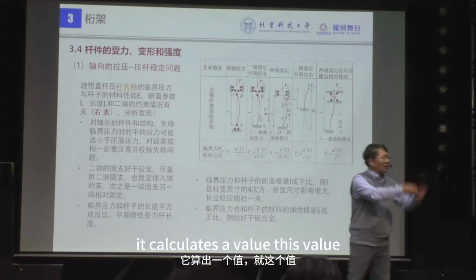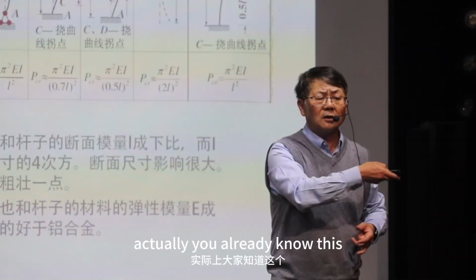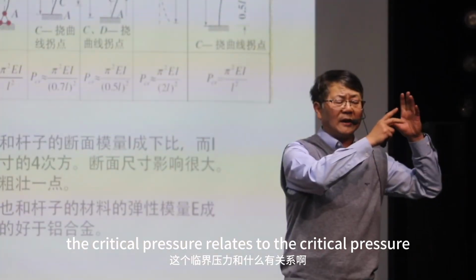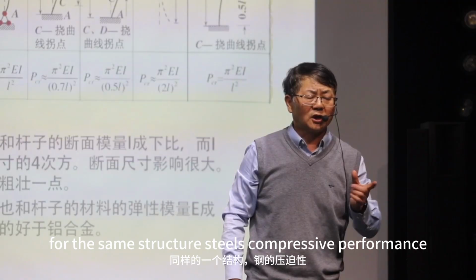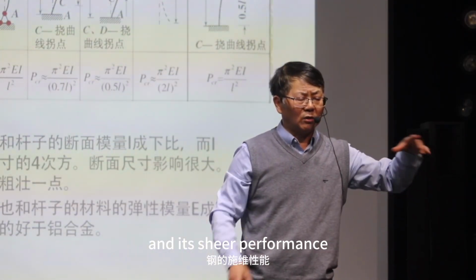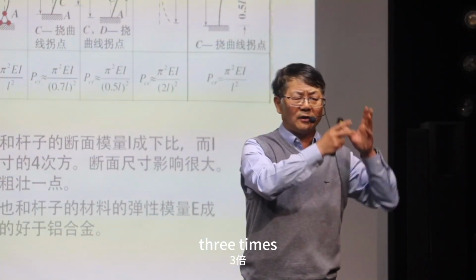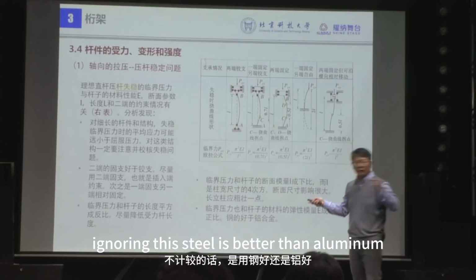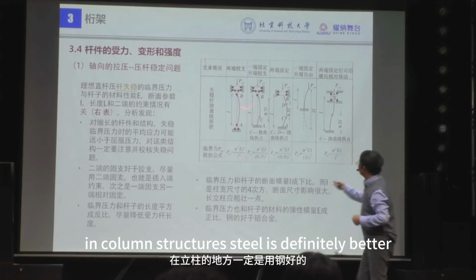It calculates a value, this value. Take a look. You don't need to memorize this. Actually, you already know this. Look here. The critical pressure is proportional to this elasticity. For the same structure, steel's compressive performance is 3 times higher than aluminum. So for columns, if you're not concerned about the cost, steel is better than aluminum. In column structures, steel is definitely better.